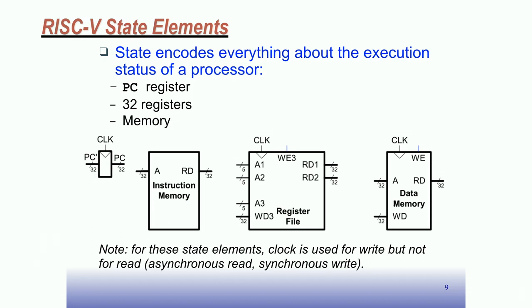The register file here, you can think of it as a collection of registers, kind of like the homework we had. In this case, though, it's going to have an interesting property that we can read two different values at the same time. We'll call this a multi-ported register file. At the same time, on the same cycle, we can write a register. So it can read two register values and write one register value all at the same time. If we can do that, it can make our processor very efficient. So this is kind of a special memory. We can do this because it's small. It's hard to do this kind of multi-porting on really large memories, but we can do it on register files.